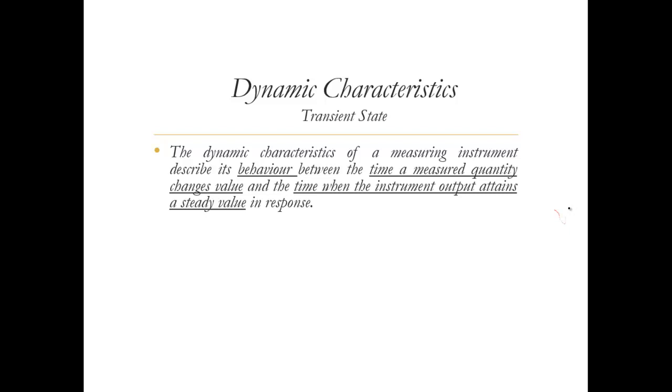We can say that it's the behavior between the time a measured quantity changes value and the time when the instrument output attains a steady state value in response. So now let's assume we have a simple case where the input really doesn't change much, but the instrument has a design because of which it takes some time to reach the output value. So this will be more clear with the other examples.